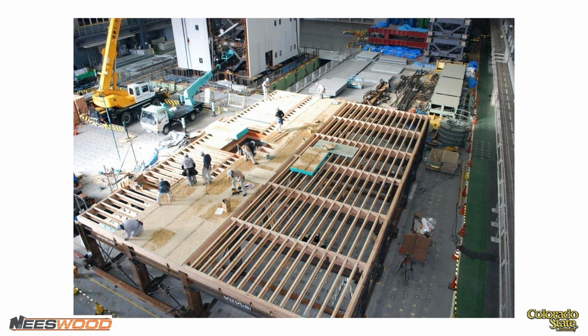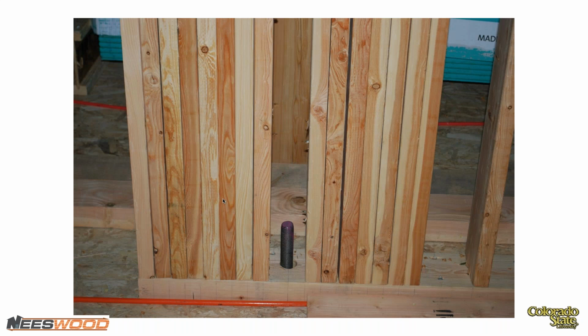And so here, this is just construction going in. You can see the shake table at the top, some damper tests and other things going on. This is the bottom floor, the bottom wood floor, and this is our largest stud pack. So this is going to get 2 and 12 nailing on both sides.